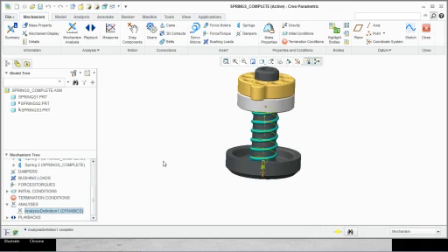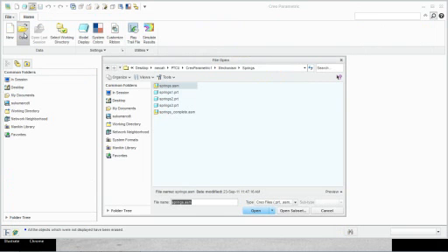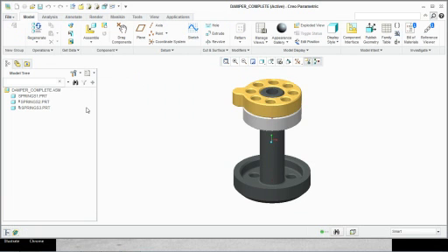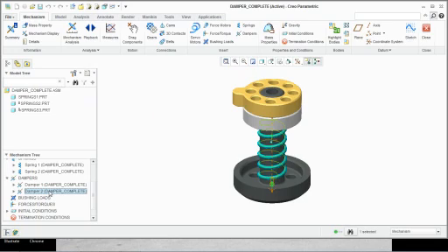So let's also look at dampers. Dampers are also something that people don't use as much, and they're pretty cool. They're very easy to use too. So we know we have these two springs in the same example. Now I have a damper. See, I have a damper for the extensional spring and I have a damper for the rotational spring. Not necessarily that I have both, but I just have it as an example. So let's look at this. Notice it's a rotational damper. That's the connection axis, and the C value.